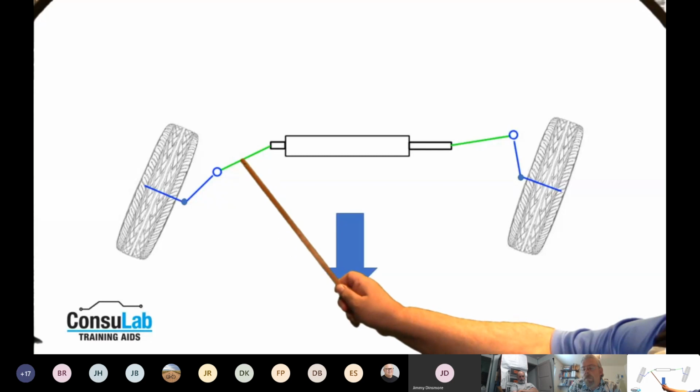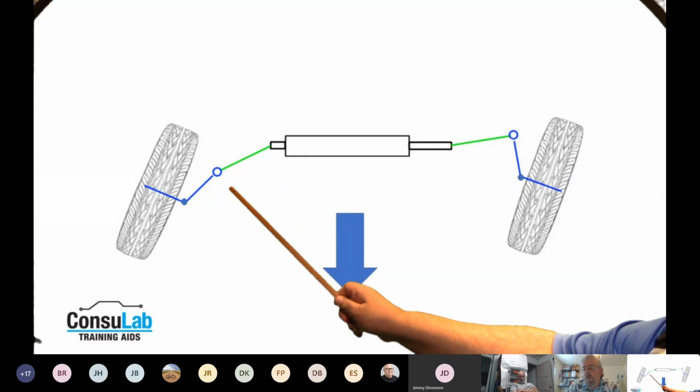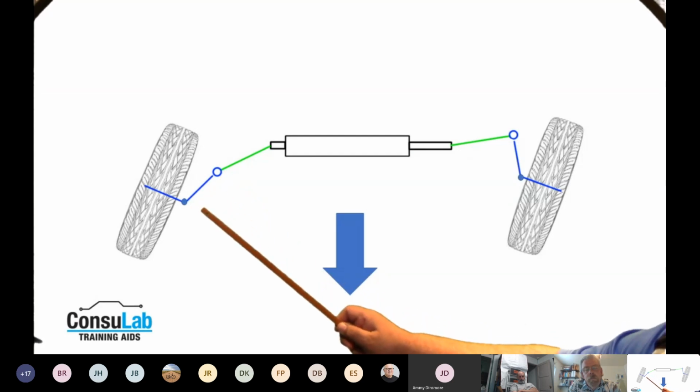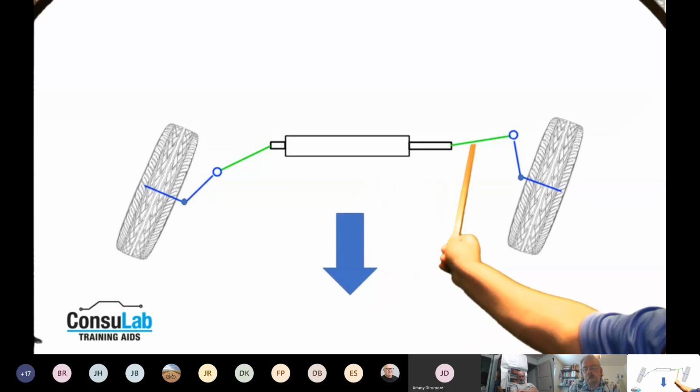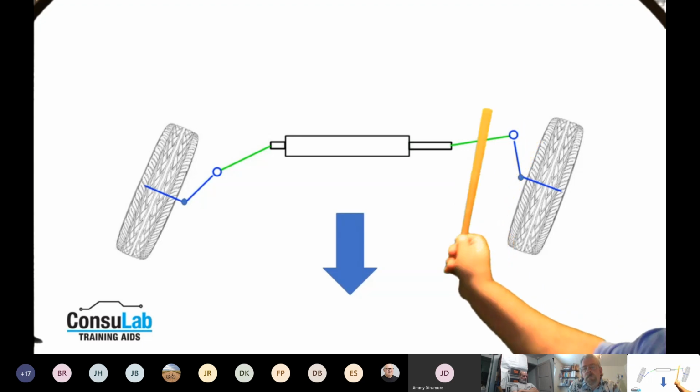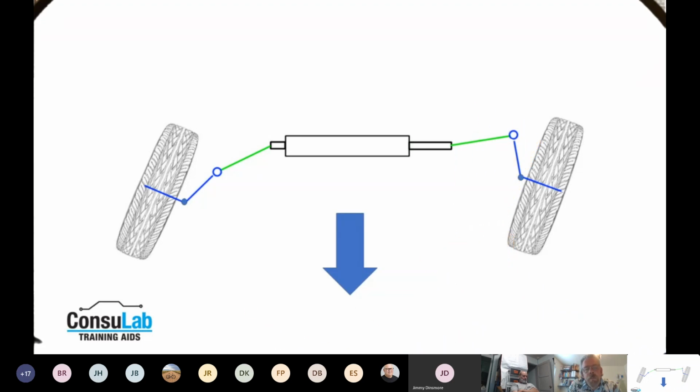So by moving this, and really what happens here is the position here, as this one moves, it moves in a little bit less linear fashion, is actually going to cause this wheel to turn a little tighter, whereas the one on the other side is going to travel a little bit more this direction and have a little less effect on the amount that the wheel turns.